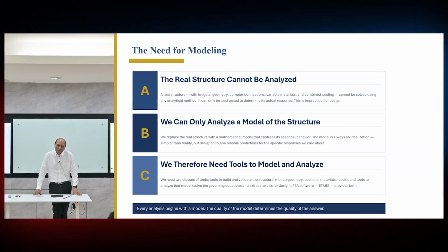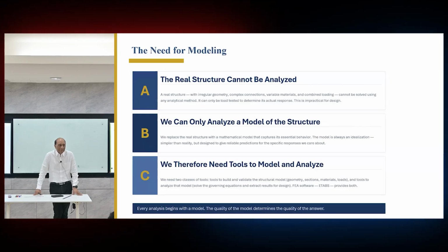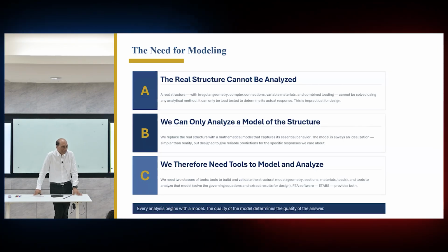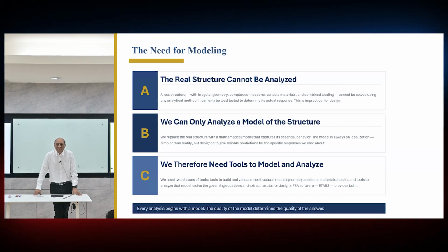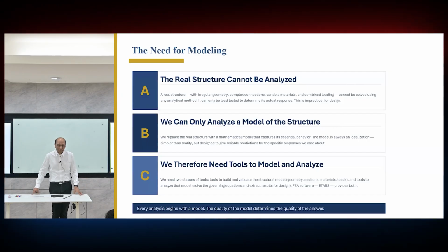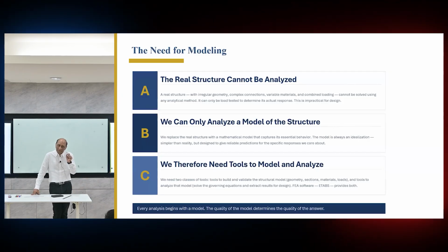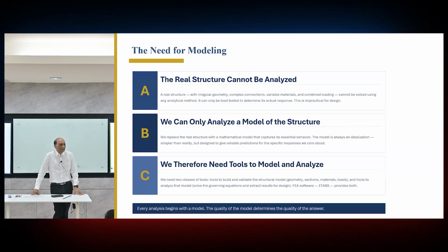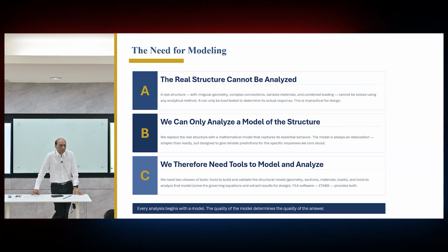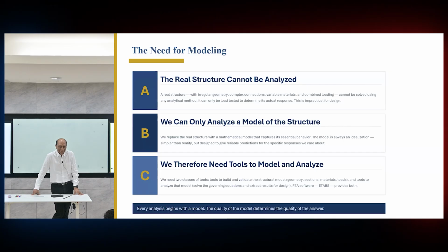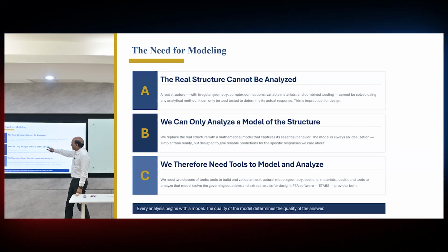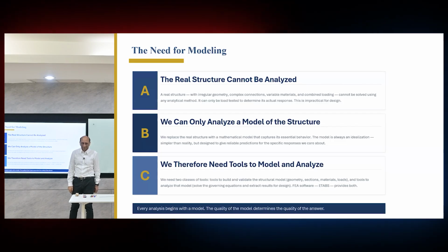Basically test it. Structural monitoring is fine, same thing. Measure it. Test it. You can't do it before the structure is built. What we are trying to do is something about a structure which does not exist at this time. That means we are only working on the model of the structure. So please never forget that you are always working with the model of a structure, and your response, your results, everything is just as good as your model. Nothing better than that.